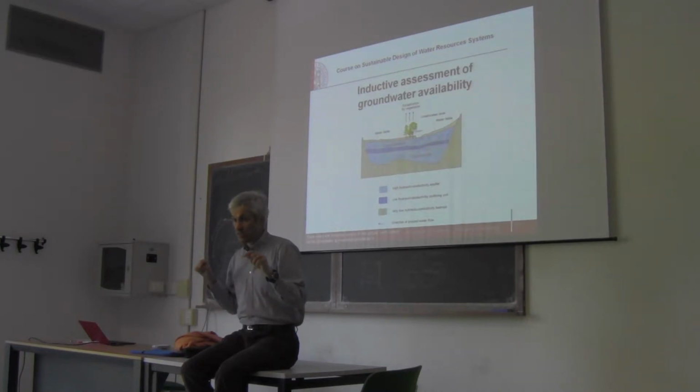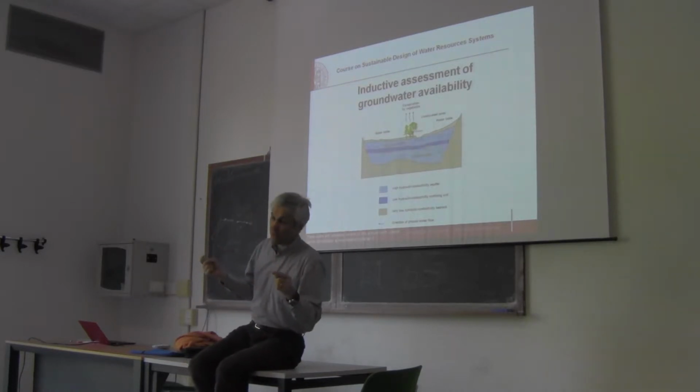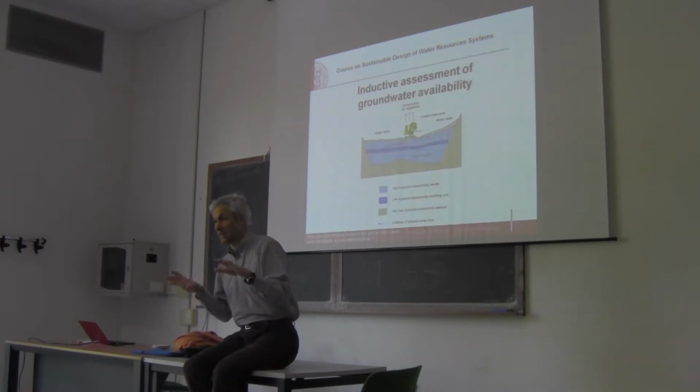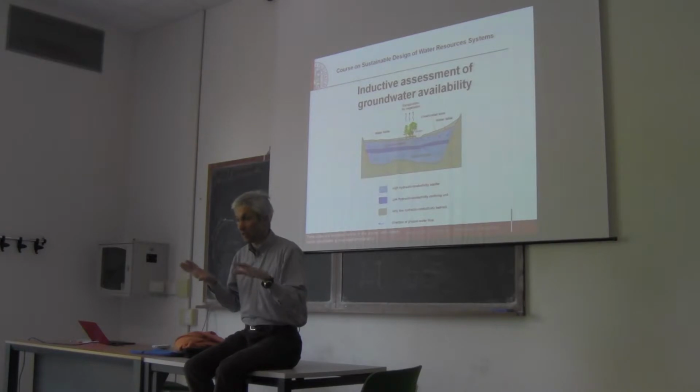We realize that this is very useful because by looking at the level of the water table in a well, we can understand the state of groundwater resources. For this reason, sometimes we excavate very small holes to reach groundwater resources which are not conceived for withdrawing water.